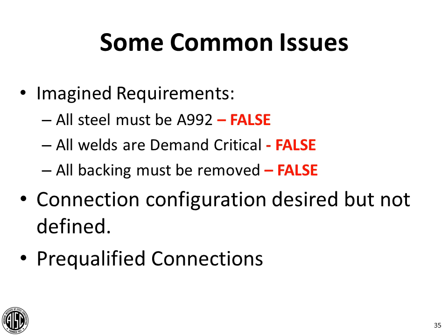And the plates and angles and some of the other connecting material probably is not going to be available in A992. So requiring all steel to be A992 on your contract documents essentially means that no one will be able to build the project that you've outlined in your contract documents.